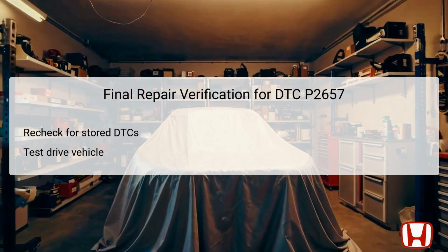Pay attention to engine performance, responsiveness, and listen for any unusual noises. If no new DTCs are logged and the vehicle operates without issues, the repairs can be deemed successful, restoring proper function to the engine's variable valve timing system.